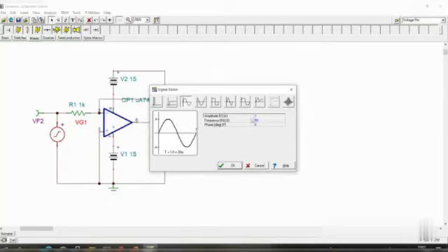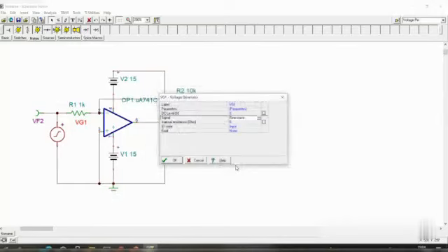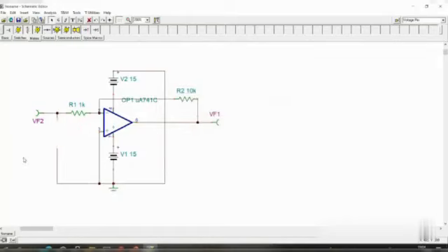So here you will decrease the voltage because you are giving a gain of 10. The output should not be clipped. So here I am giving, for example, 0.5 volt, just half of the default amplitude. And the frequency I am giving, for example, 1 kilohertz. You can give any frequency and check it. Accordingly, you have to set the output. That's it. Now this VG1, the voltage generator, is fixed to a sine wave with an amplitude of 0.5 volt that we have given. That will also be shown while you are doing it.